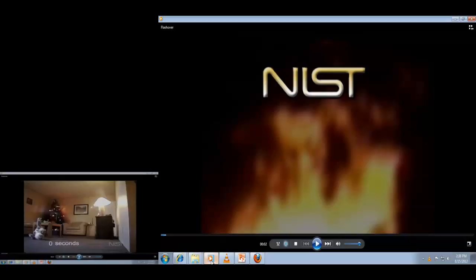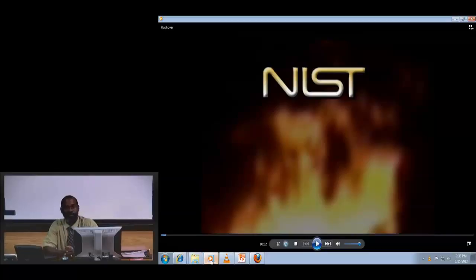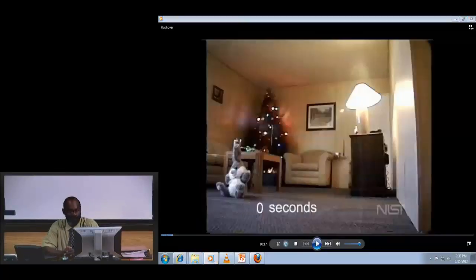So before starting, I want you to all come to some determination for yourself. One, what does it mean for a room such as this living room to become untenable from the perspective of fire? Two, how long do you think it's going to take if a small ignition source, a small lighter that's placed at the bottom of this tree, how long is it going to take before this room becomes untenable? And finally, we've talked about flashover, for example, in this last lecture. How might you identify flashover for a compartment like this?